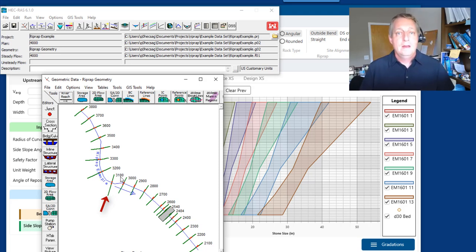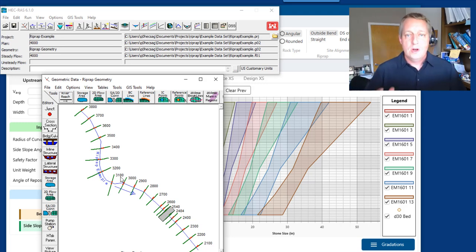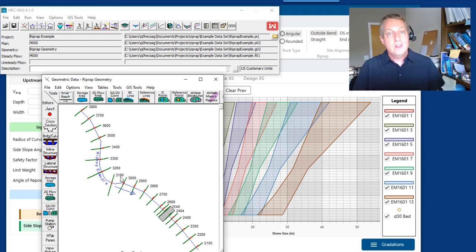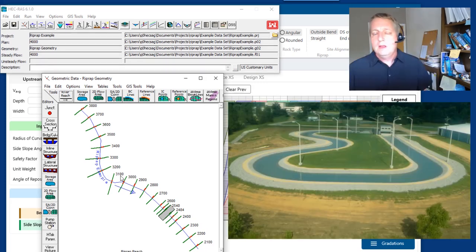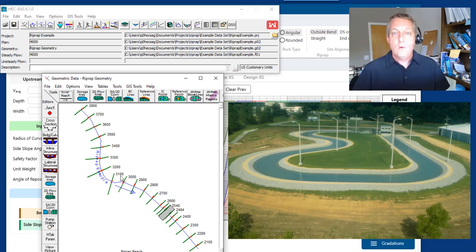But the Maynard equations were not developed for the velocity at the cross-section itself. The velocity at river bend cross-sections is fundamentally multidimensional. There's lots of helical flow stuff going on. It's just not a one-dimensional problem. And these equations were developed for not only one-dimensional flows, but idealized one-dimensional flows.